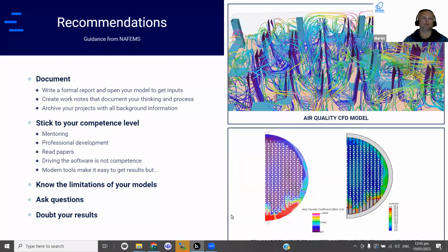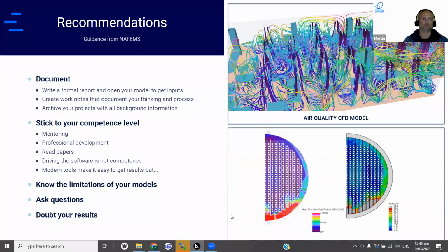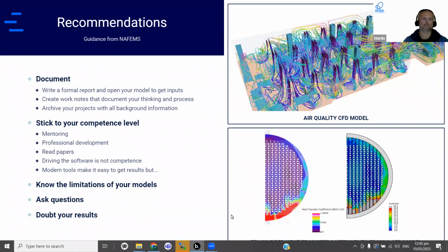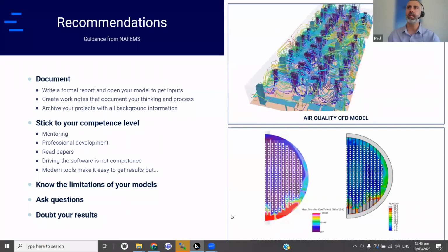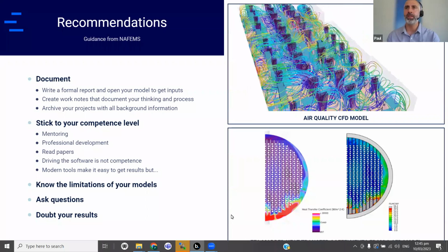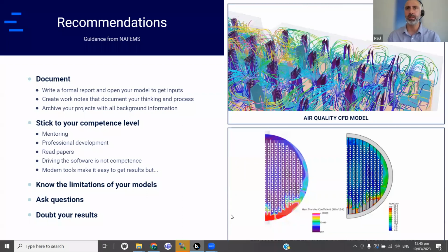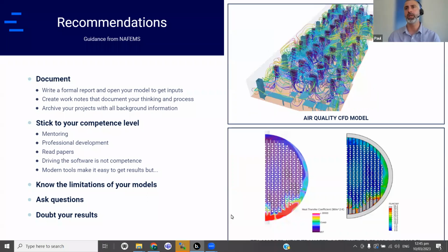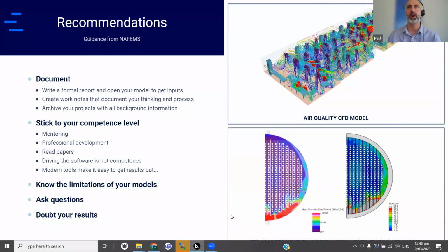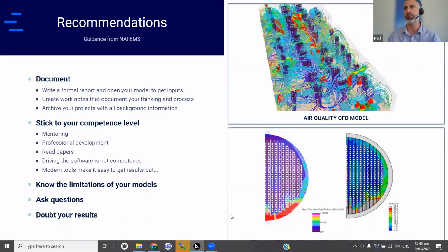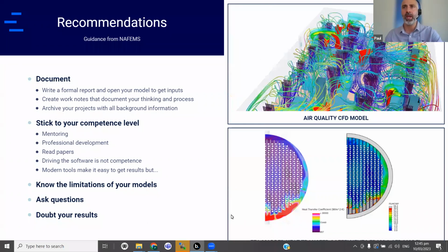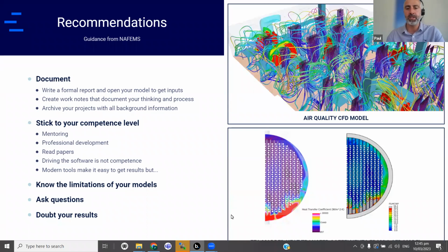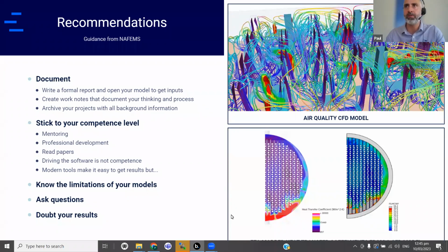And the next question is, as someone who has an academic background in simulation, how would you recommend getting started at a professional level? Any recommended starting points? In terms of professional level, I think you would start with simpler analyses. I presume that you're working as an engineer in that environment. If you're working on real problems, start with simple problems, problems that you think you can get a good answer with, and compare with hand calcs. I think those sorts of things will help you build confidence.